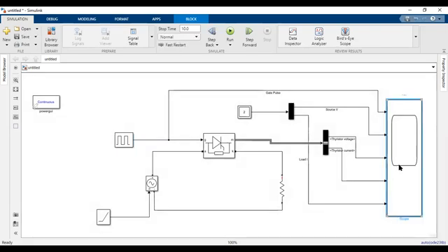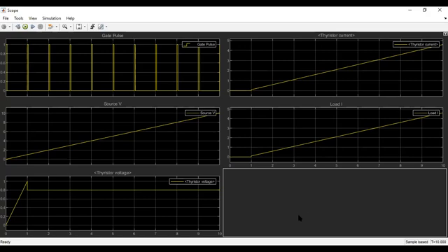Double click on the scope. Now the scope has been shared. See, it breaks at 1 second. See, the first pulse is at 1 second. Therefore, there are a number of pulses. There are 1, 2, 3, 4, 5, 6, 7, 8 pulses on our screen. There are more. It will go on. Nothing occurs here. It means once the junction is broken, the thyristor starts conducting. Once it starts conducting, there is no use of the gate pulse. Right?